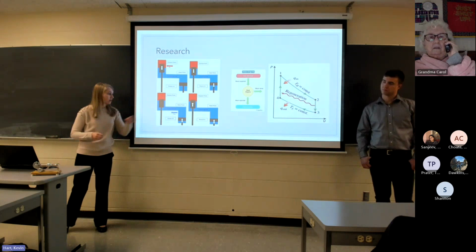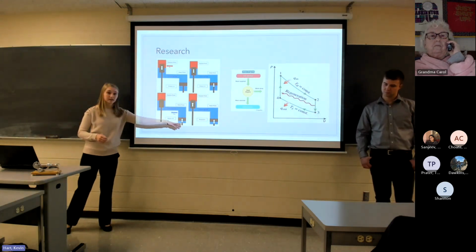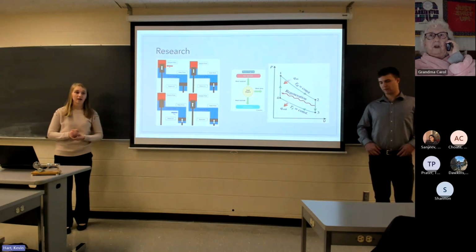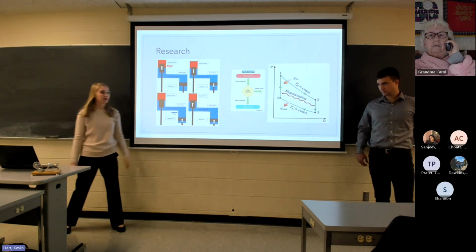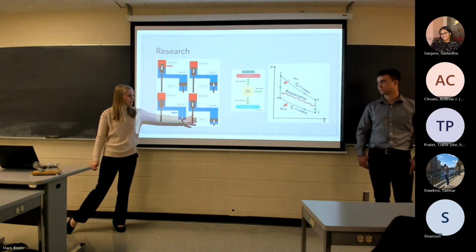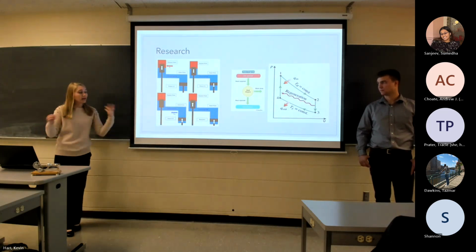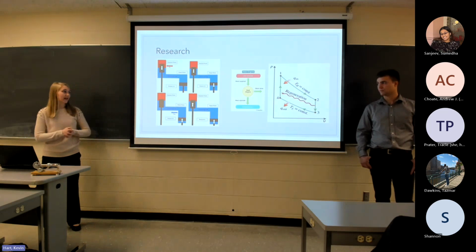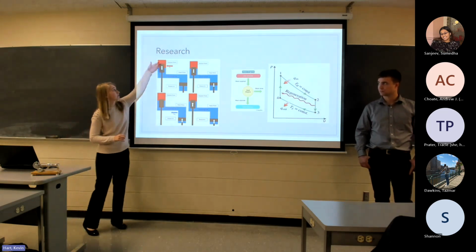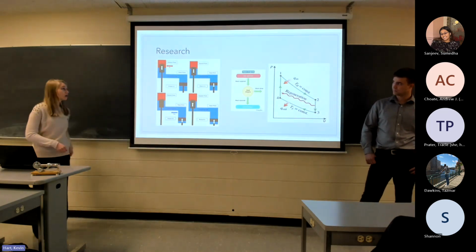where heat is leaving to the cold reservoir, and now we have the constant temperature, so we have the compression of our power piston. And then similarly, we have another isovolumetric phase where both of the pistons are compressing. So that kind of sums up what exactly is happening with the gamma type Stirling engine. The regeneration process is between the hot and cold reservoirs in the displacer piston as well.